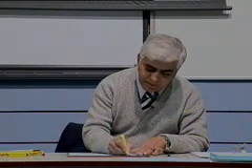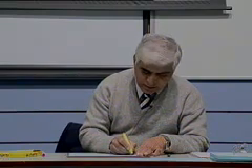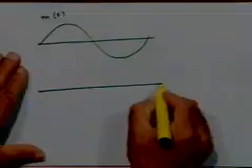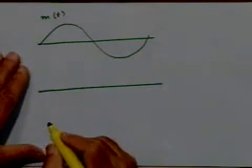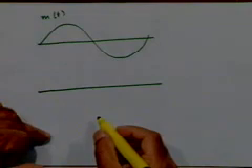But for the sake of our simple discussion here, let's assume that our message signal is a sinusoid of low frequency. Since it is to be a low pass signal, we will represent it by a low frequency sine wave. Right? So let's say this represents your m(t). And let's try to now depict the modulated signal, which is m(t) into cosine omega_c t, right?